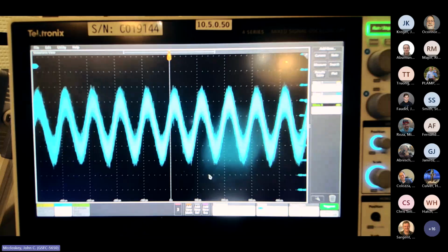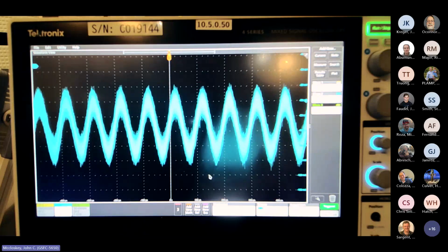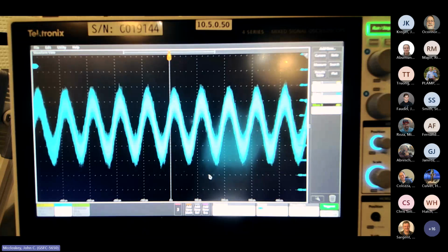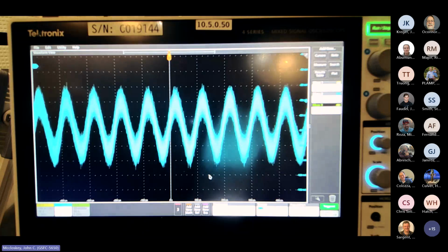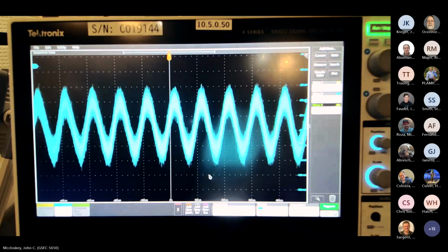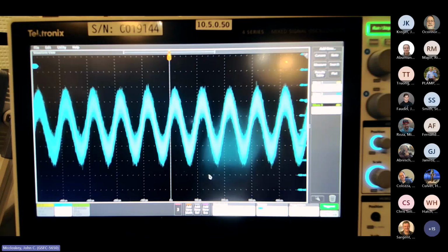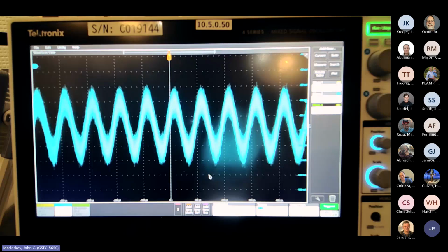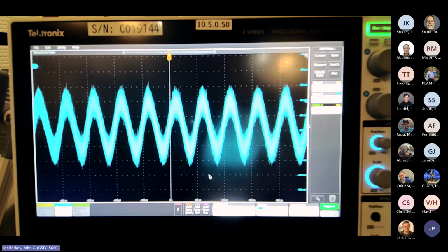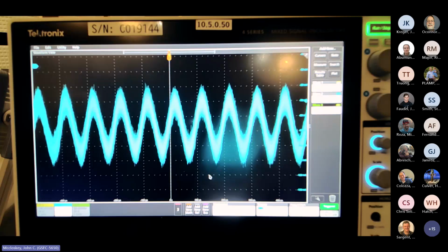So it's a little high, but remember that I did adjust the level intentionally to get the desired reading at 100 megahertz. So at these low levels, we may run a little bit high. If that really concerns you, you could adjust the level down a dB or so, but then you might have an undertest up at the higher frequencies.